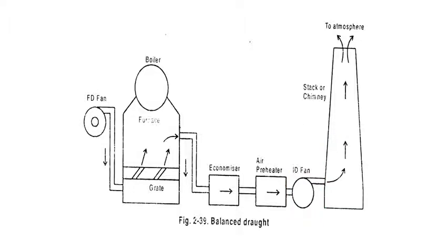One more point to note is that when we are entering the furnace or when we want to check the furnace, we have to take care of the draught before opening the furnace, right? Surely we have to take the engineer's permission, and monitor the draught system. Then I can visualize or monitor the furnace. Otherwise the flame may come out of the furnace and it is very dangerous.